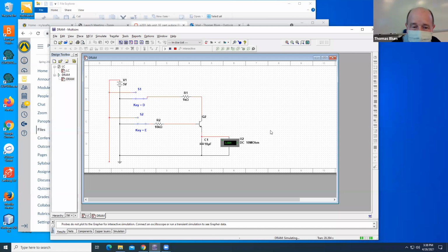And then the significance of that is that we know that DRAM requires refreshing, that it doesn't always do a good job at holding its voltage, and therefore it occasionally needs refreshing. That's the significance of the changing, is the requirement for refreshing of DRAM.